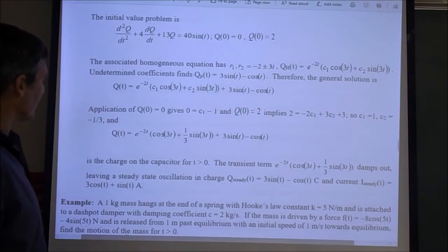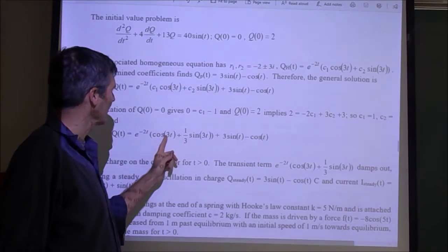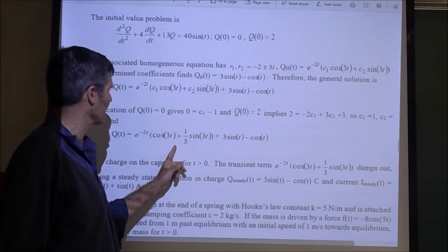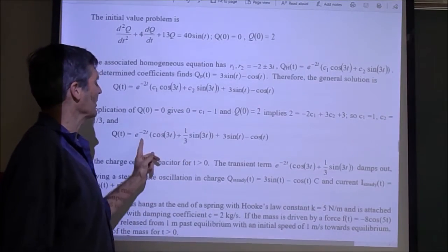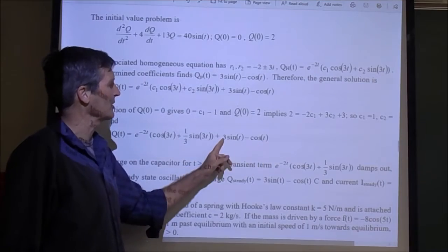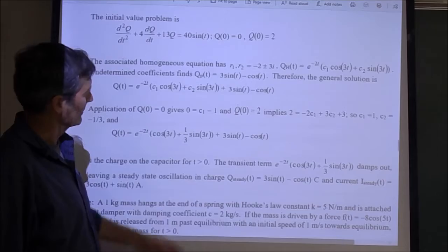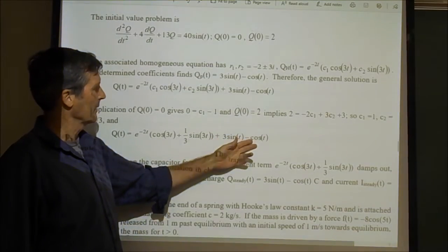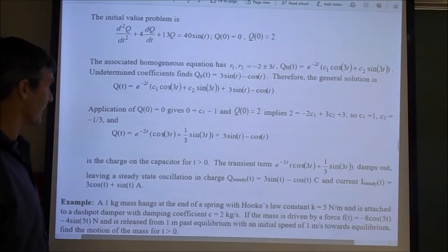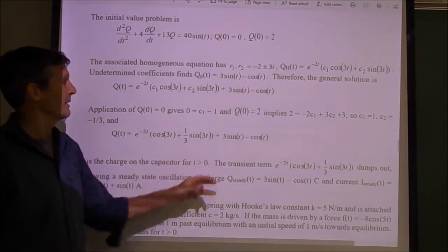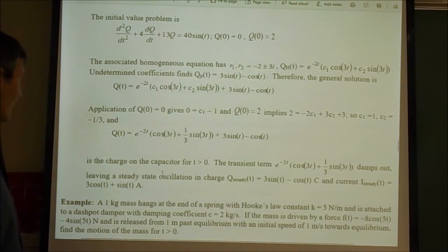All right, now what you do is you look at that and say, this is a sine wave, right? Same frequency, a single sine function, times a decaying exponential. This is the transient term. This one is a single sine wave. We could again use the formula from trigonometry for that and write that as a single sine wave. We call this the steady state term.